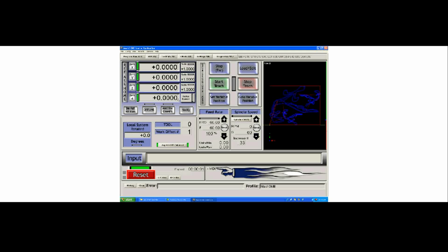Radius correction is used for 4-axis work, where you can tell the system the actual circumference size of the object, and it will correct the feed rate to create a toolpath that feeds at the correct rate on the circumference of a rotating object. Again, something that you can ignore unless you understand what they're for.